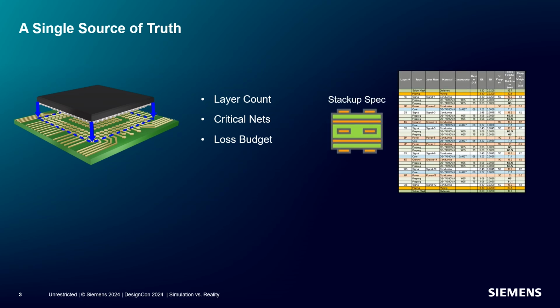And all of your simulations that you're going to build your board on are based on the assumptions you make here. How accurate this spec stackup is depends upon how diligent you are in your data process. If your end goal is to have your fabricator ultimately build your board without relying on the design you create here, then all your simulations have started out incorrect. Our goal with zPlanner Enterprise is to build the most accurate stackup possible, to have it reflect real materials, and to have it built upon the actual fabrication process that will be used to construct the board.